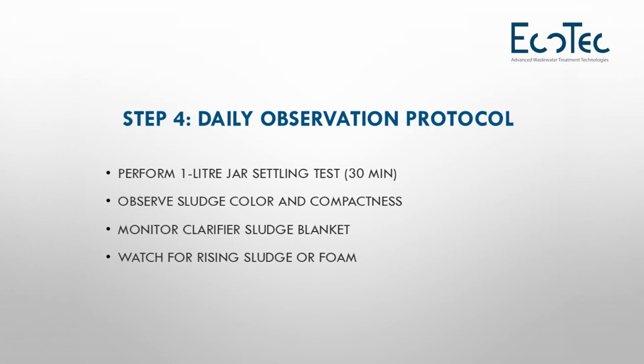Regardless of technology, extended aeration or ASP process, observation is fundamental. A simple 1 liter jar test in suspended growth systems can reveal the sludge health. Watch the clarifier for sludge blanket. This gives you an understanding of how the plant is functioning. Foam formation should be monitored.